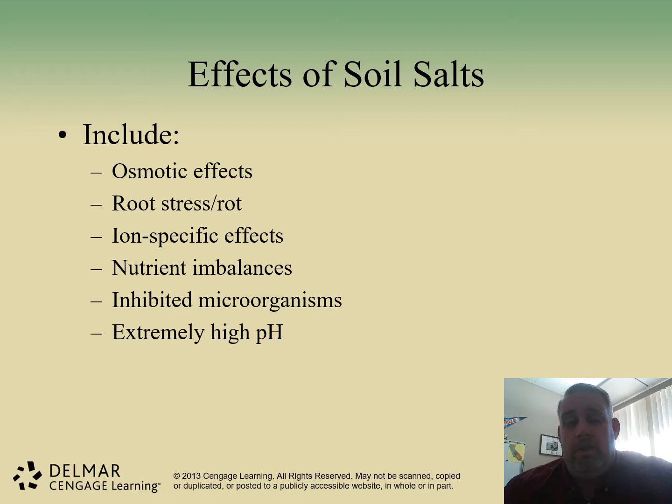Salts are an inhibition to microorganisms. They can actually kill them, kind of like when we pour salt in our wounds, we don't like it. Our microorganisms don't like salt poured on them, so we have to be really careful not to accumulate these salts within the soil, and if we have that problem, we have to percolate and wash that salt out of the root zone of the plant. Salts can also include a very high pH because of the different minerals that contribute to your total dissolved solids.